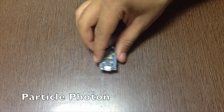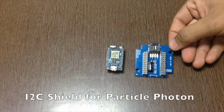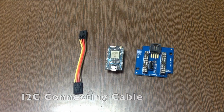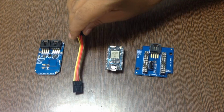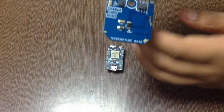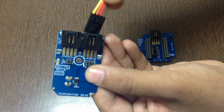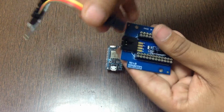Now this is the particle photon module, and this is the I2C adapter that we use to connect to the I2C devices, and we make the connections using this I2C cable. And here we have our sensor ADT75. Now let's make connections between the I2C adapter and ADT75. First let's take a look at the sensor. While making connections, please make sure that the brown cable of I2C wire gets connected to the ground of the sensor, and similarly for the I2C adapter too.